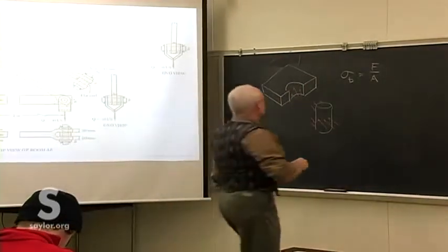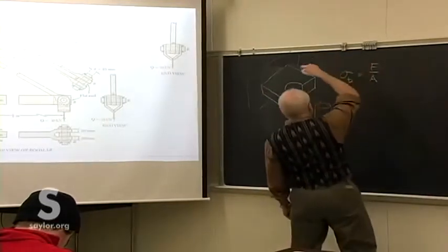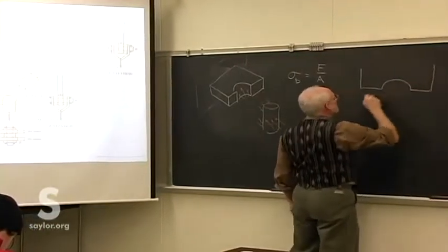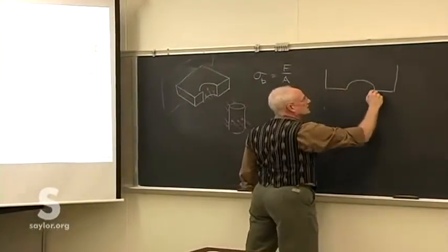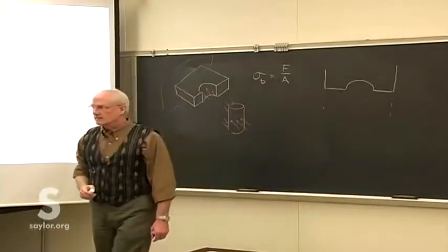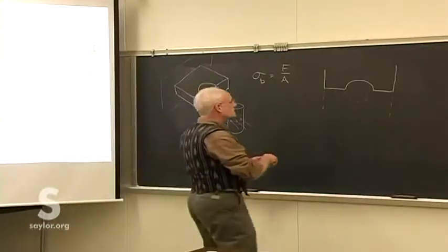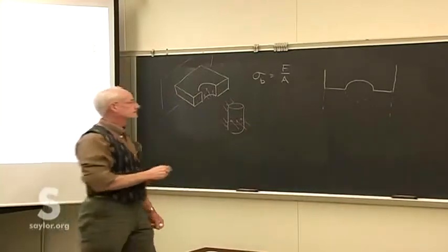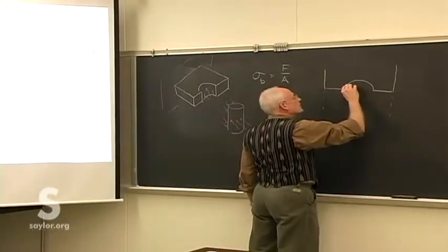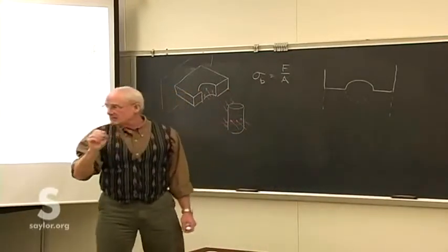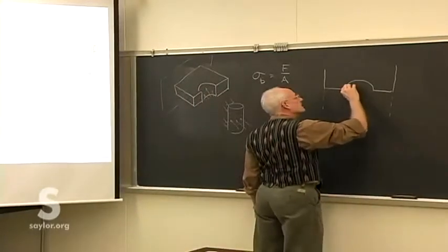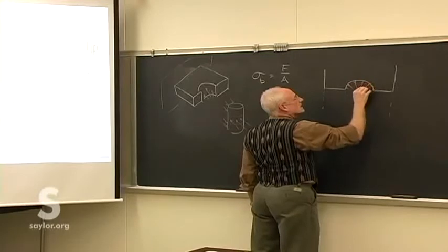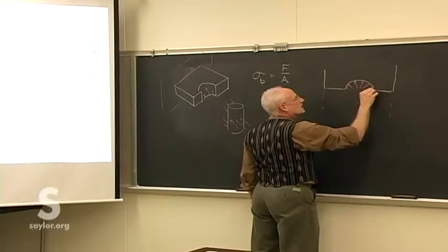For this bracket, things are a little bit different. I'm going to change the view some. We're going to look straight down on the bracket there. It's a little bit easier to draw. Remember, this is a cross-section of the bracket where I'm looking at just the bearing stress of the pin on the interior surface of that bracket where it meets. It's not a uniform force distribution, not in magnitude or direction. As it presses on the interior surface here, it changes a little bit with position.